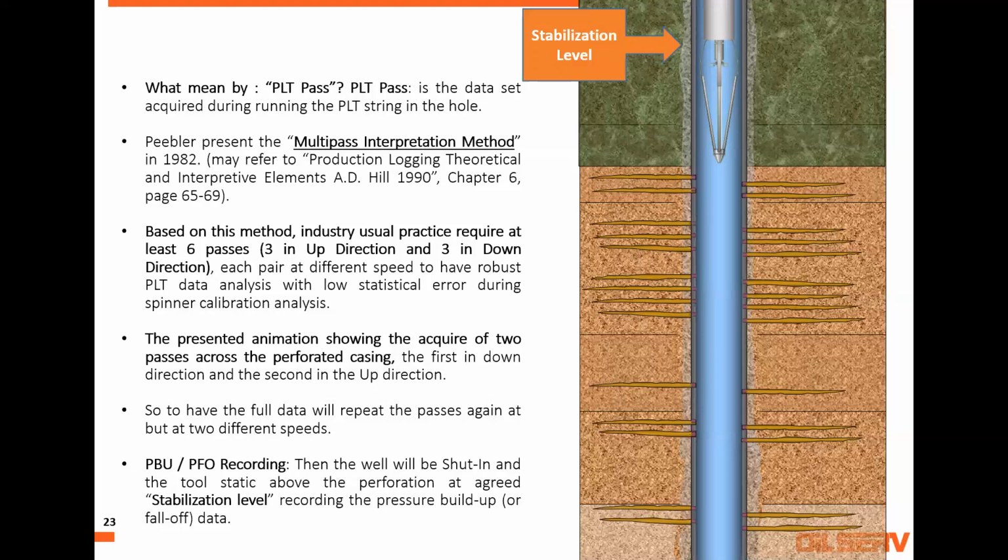There is actually a reverse situation to the one you mentioned. Some wells produce 500 barrels, 400 barrels, and the flow meter will not rotate. This is a super low flow rate, even below the spinner threshold. Maybe this spinner needs 50 or 70 barrels to start rotating.